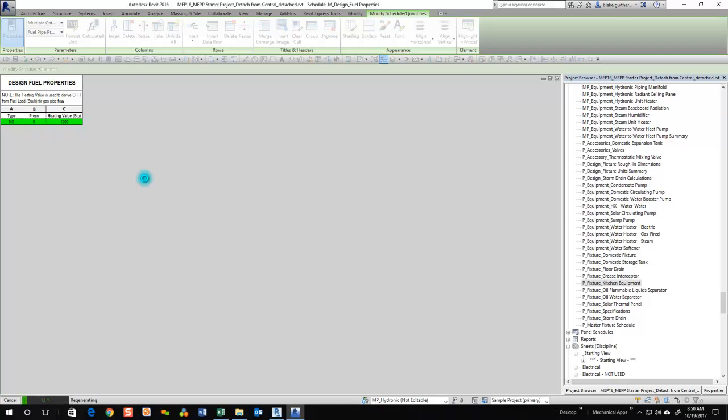We have included a heating value. We went through the gas-fired heat exchanger calculations, but we didn't really talk about this value. This value does not have proper data types yet because they're not available from Autodesk, but essentially it's deriving the CFH value from the BTU value. In this case, we put the units for the parameter up in the header here. So this is a BTU per cubic foot value. 1,000 is fairly common throughout the United States, with the exception of, once you get into higher elevations, Colorado and places like that. This also allows you to calculate CFH with different types of fuels. So if we had propane, we could change the type here to indicate propane, and we could update this value, and now all of our CFH values and all of our gas riser diagrams that are being counted from the BTU load will update.